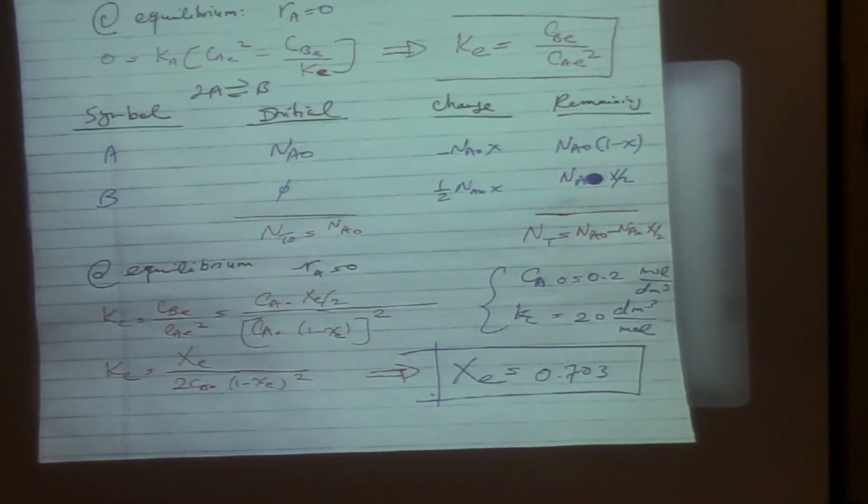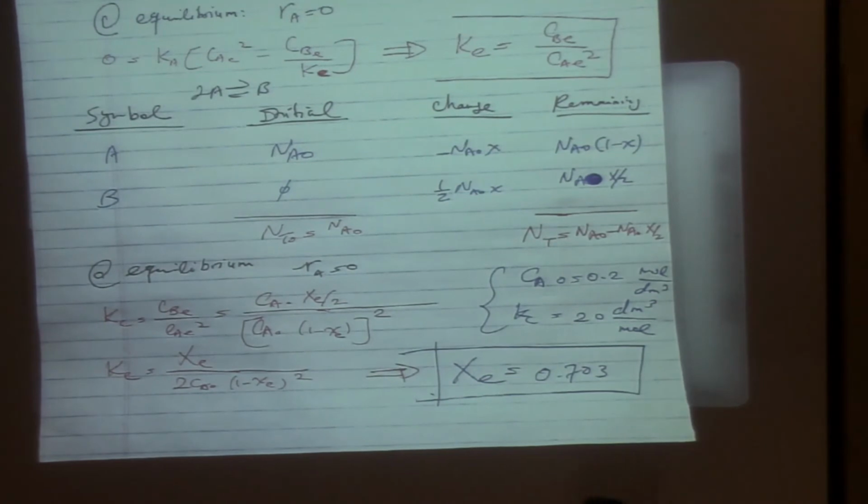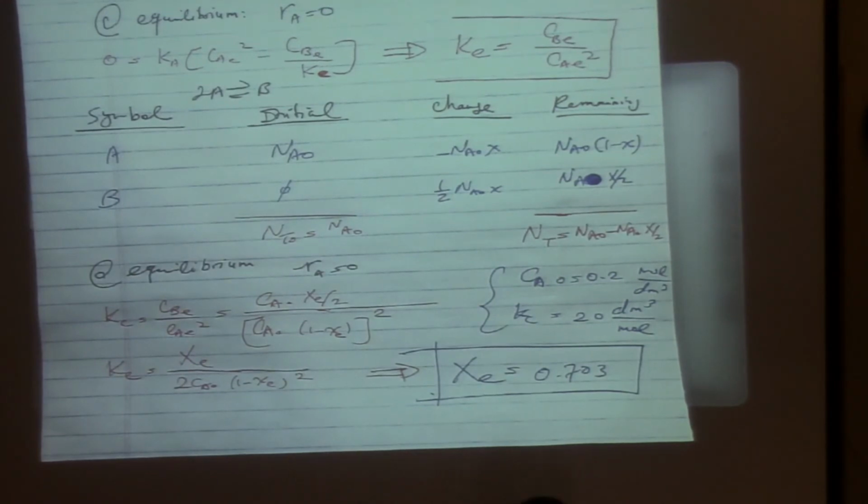Okay, I'm going to flip the page, so write it down. Just for the sake of completeness, I'm going to quickly put the same stoichiometric table for the flow system. Exactly the same, nothing is going to change. We were dealing with the moles in the previous table. Now we are going to replace the moles with F, which is the flow rate of each component for the flow system.